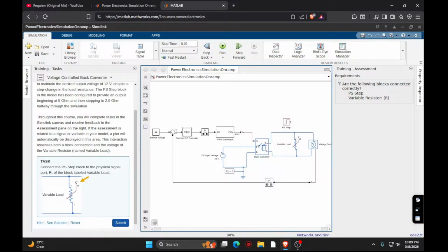It is connected to the comparator, and the comparator is connected to the PID controller. A PID controller is a type of controller which can control the signal via feedback, with proportional, integral, and derivative terms. After that there is a rate transition, then there will be a PWM generator. So basically the voltage is going to the rate transition, which is connected to the PWM generator. The PWM generator will generate the PWM, and that will go to the buck converter, which is the fast switching.